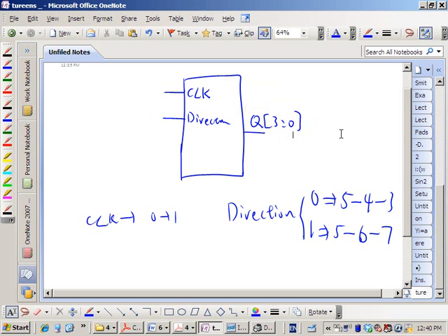And that stands for 4 bits. And we can also add this input of D[3:0]. And this decides the initial condition of the counter. For example, I have to start either from, like in this example here, I start from 5. And also I can write a different number into the counter. For example, I can load number 4, then we start counting from 4, right?